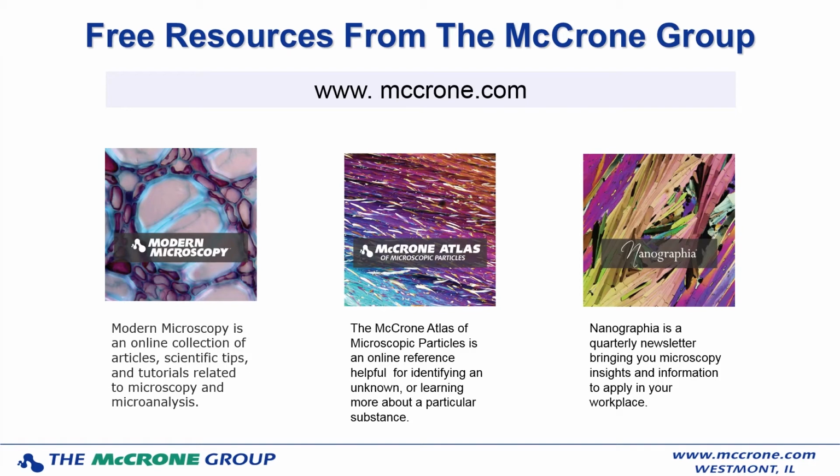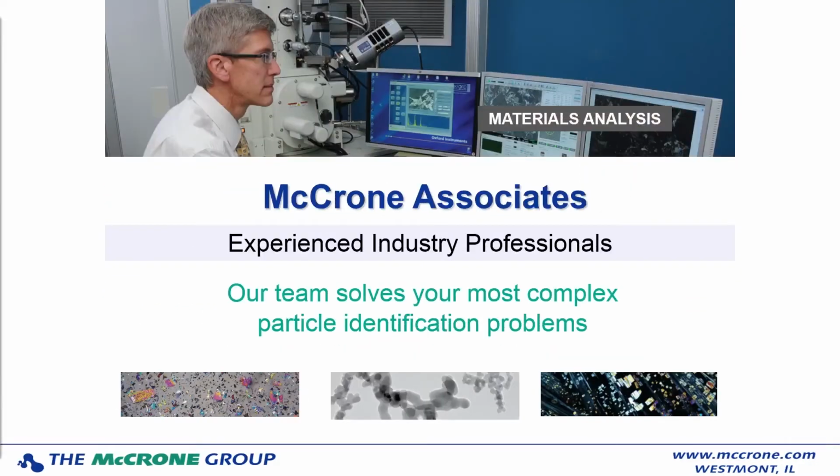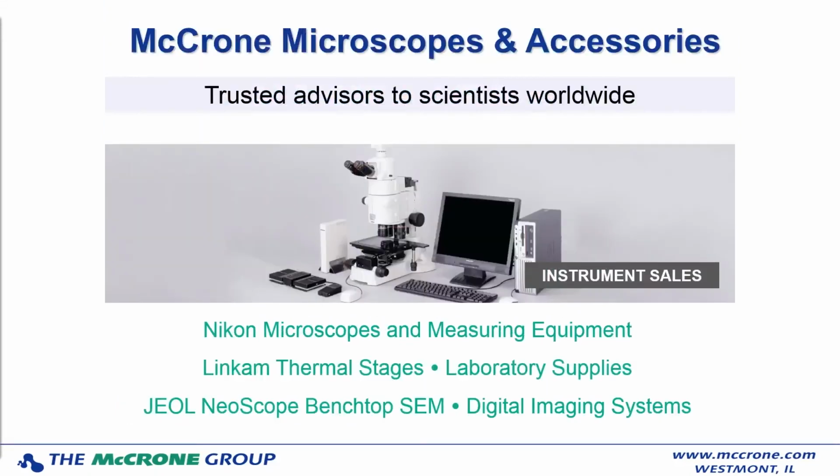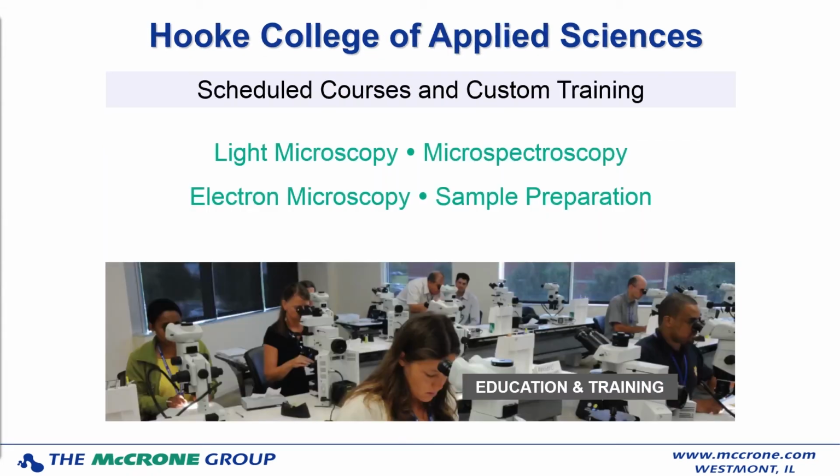Third question, how is this technique used for glass delamination of vials? Great question. So this is an area that we've done a lot of work on, and typically what we're using XPS for is not looking at the glass flakes that are generated by delamination, but rather looking at the surface chemistry of the interior surface of the vials. And that can be an indication of what happened to produce the corrosion and eventually delamination of glass.